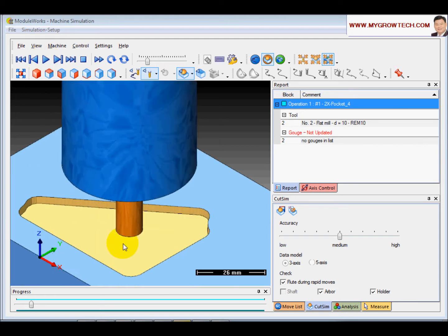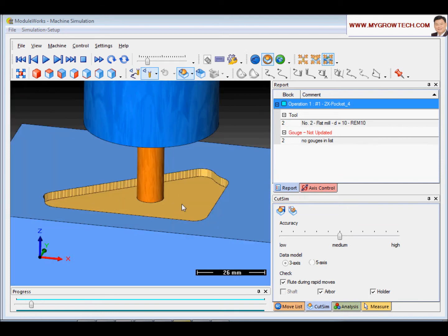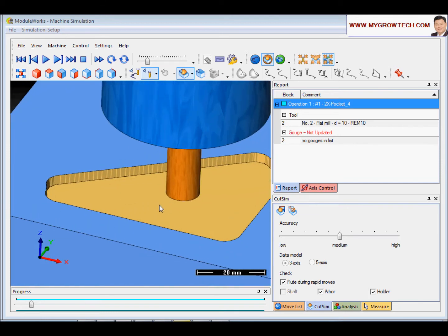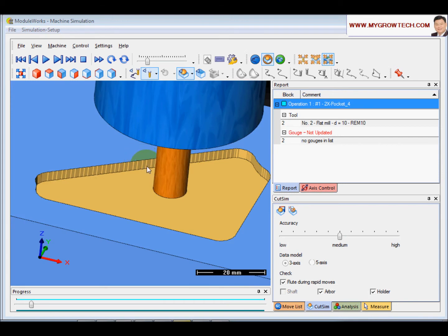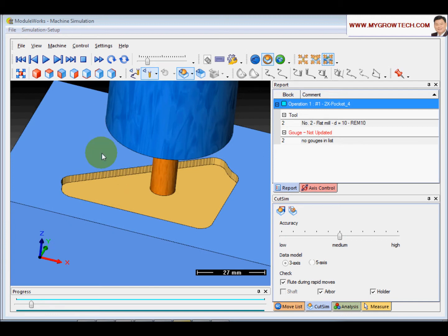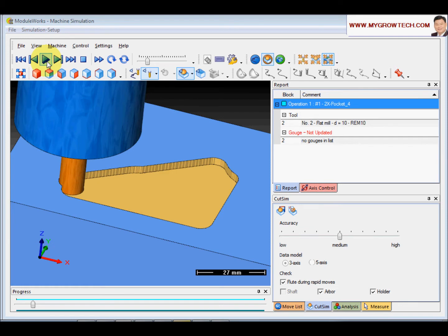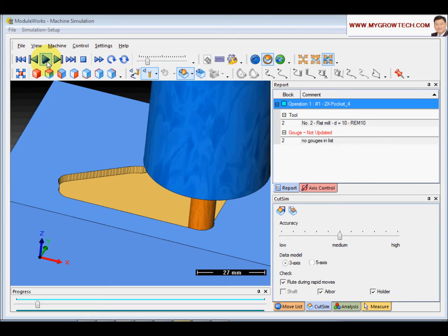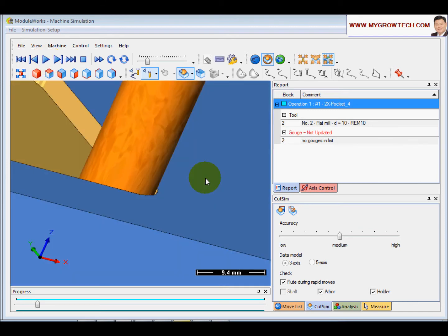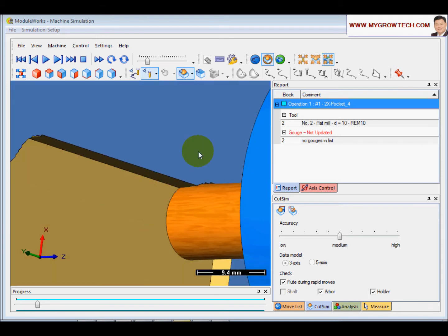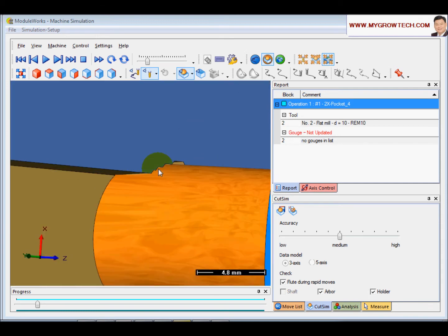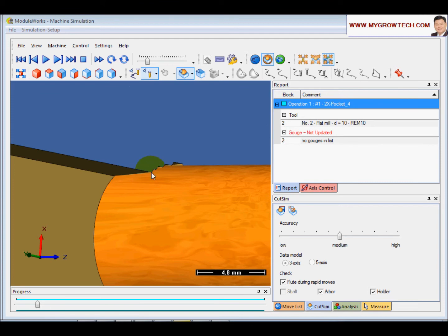After roughing each layer, C023 will leave 1 mm of material for the finishing pass to cut. Let's look again. Now the cutter, instead of cutting a 4 mm side step, when it touches the wall it only cuts 1 mm. That is the contour offset rough.